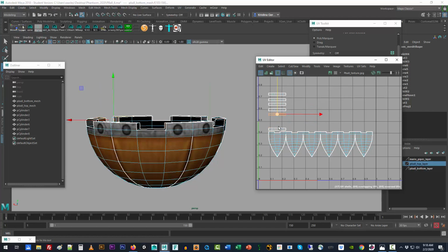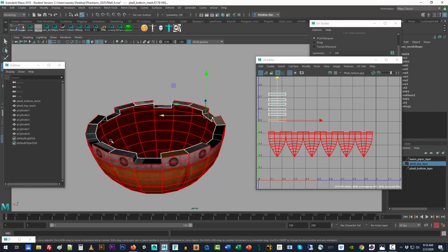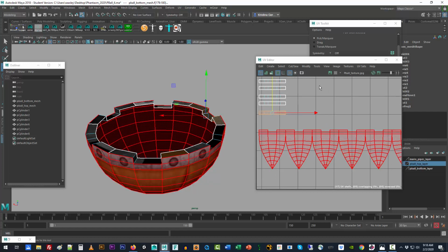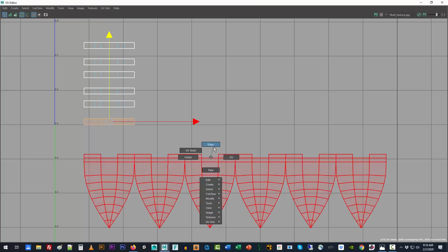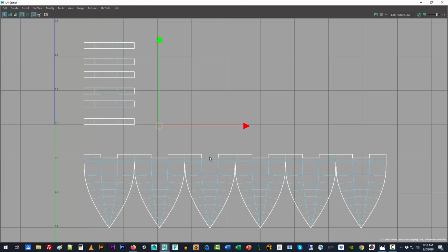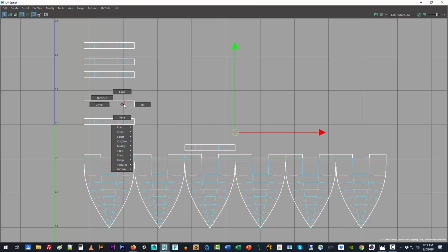We have then corresponding 6 sections immediately above it, the lip of this bowl, and we want to make sure that we're aligning them on top of all of the proper slices. So remember, when you grab an edge, you grab its corresponding edge, which again is the same one. So if you click an edge here and you see it flash in one of these sections, you know that this is the one that belongs over here to this particular section. So you can go through this and just find which belongs where, and just quickly line them up.